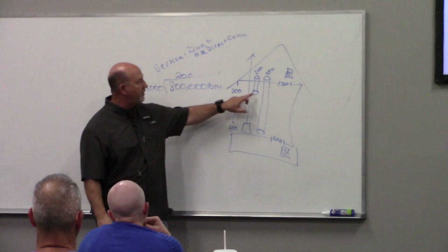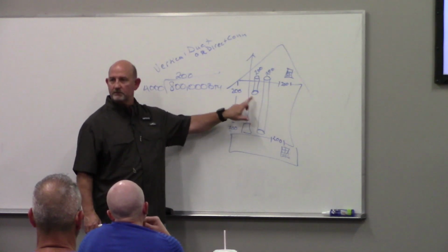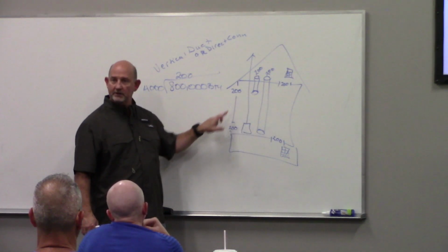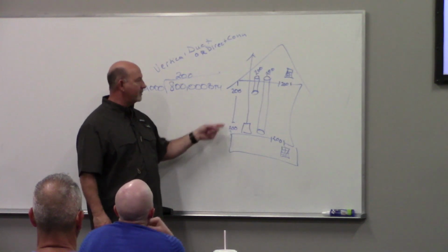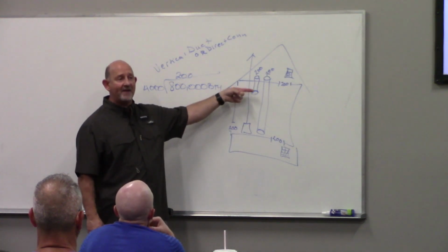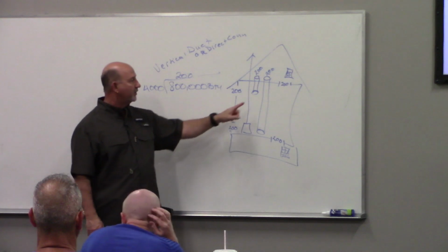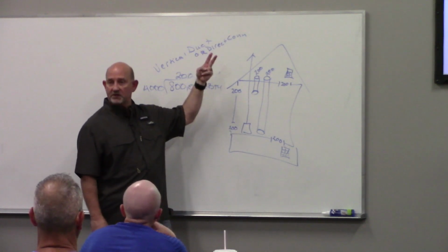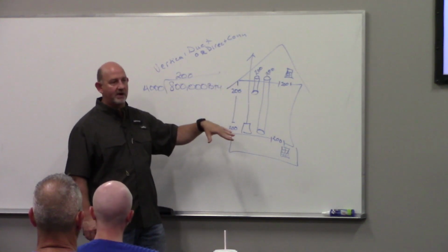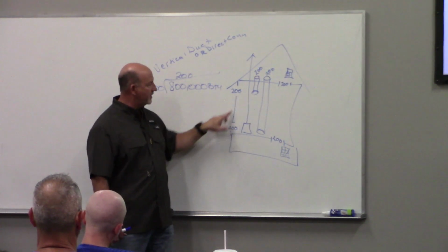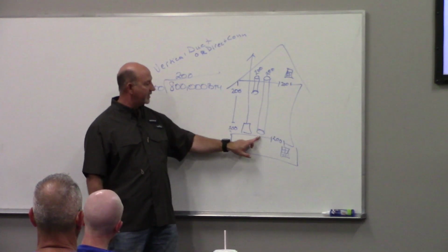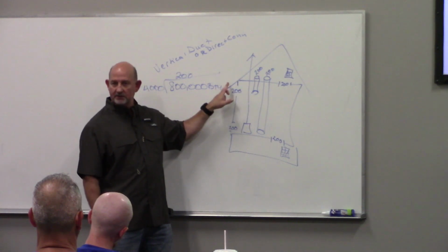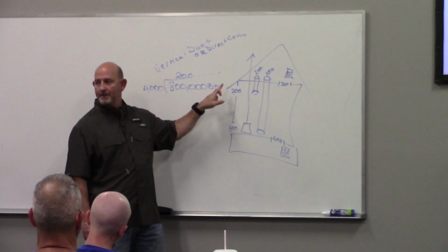So look, do you agree I can do this and this? Look up here. I can do this and this. Agreed? Because this is a vertical duct, this direct communication, so that's what size they need to be. But do you agree I have to have one in the top and one in the bottom? Look up here. Do you agree I cannot do this and this? Yeah. Because those are both in the top. Either one of those are fine, but I also need one in the bottom. So this and this are okay, this and this are okay, this and this are okay. But I got to have one in the top, one in the bottom. You guys okay with that?